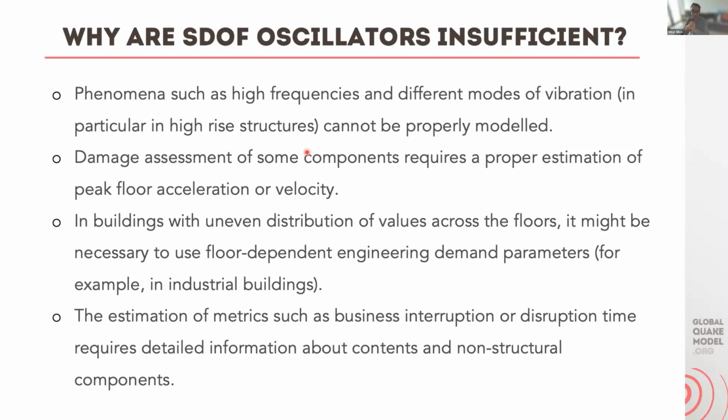And for those buildings, we should use PGA, for example, for the ground floor, and then spectral acceleration maybe for the upper floor. But clearly the single degree of freedom systems are not ideal for these cases. We can approximate some of the analysis, but again, that's what we're trying to avoid. And estimations of metrics such as business interruption and disruption time require detailed information about contents and structural components. So again, using specific EDPs for these aspects is quite important.